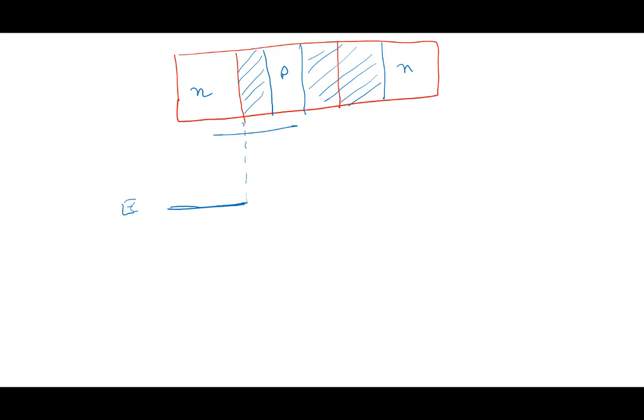Then the conduction band, and this is the edge of the depletion region. So the conduction band will go, I'm not drawing exactly, it goes like this, and then becomes constant till here. And then the conduction band will go. Let's say this is at equilibrium, so I can draw a Fermi energy, almost like here. The conduction band will go like this here. Or if I've applied a reverse bias, it will go like this here.